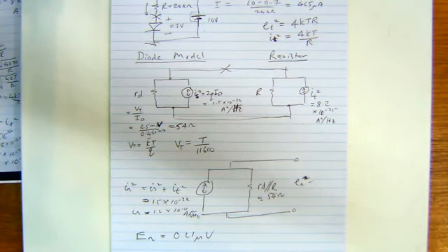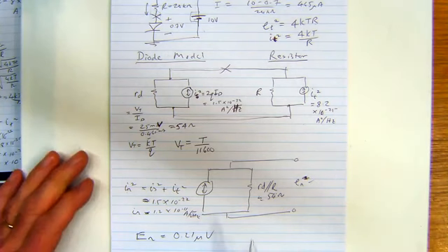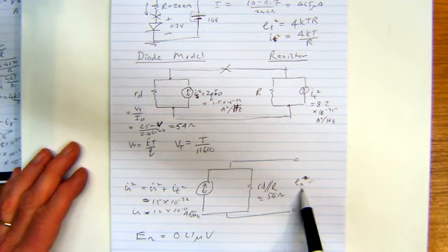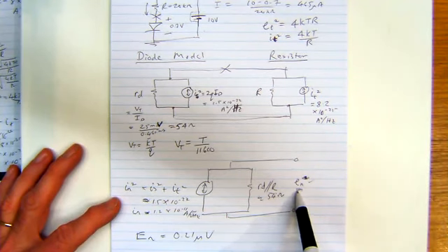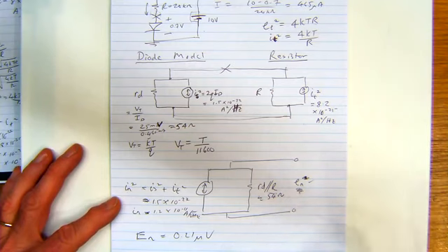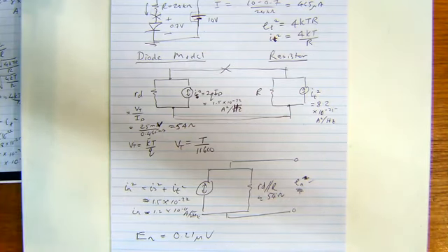It was 100 kilohertz, wasn't it? So you multiply by the square root of that. Multiply this by the square root. Oh, sorry, I'll be a bit more clear. You multiply this spot noise voltage by the square root of that bandwidth. So to get the capital E then, you multiply by the bandwidth.